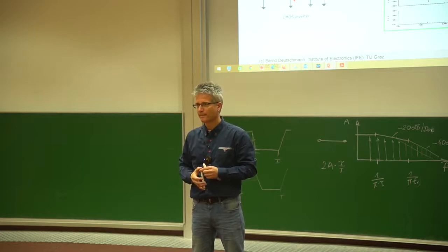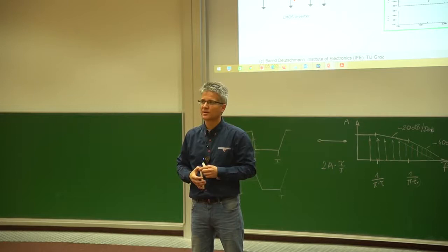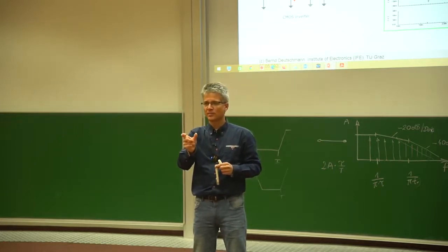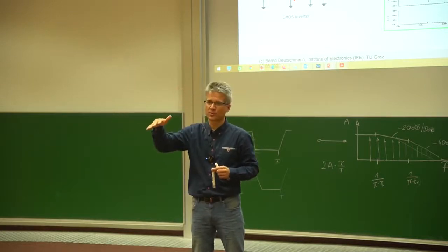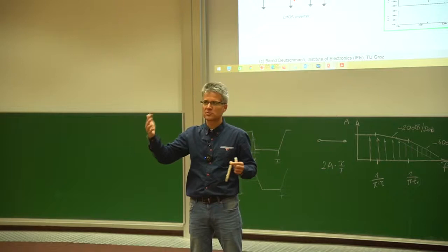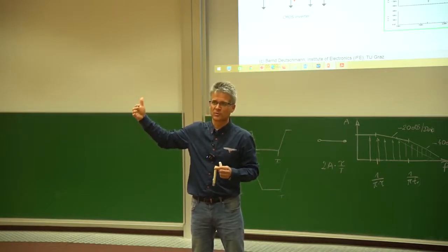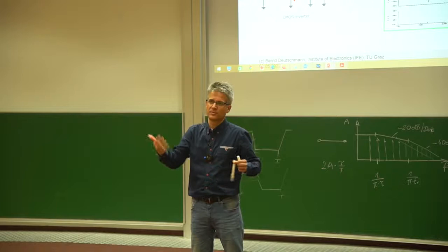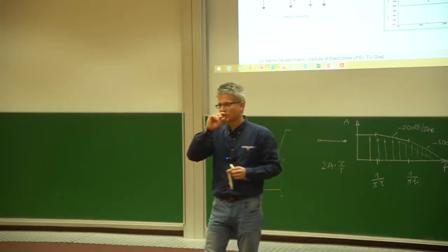Small resistance. Okay. But if the resistor is then there permanently, and we are driving, for example, a high signal at the output, we always have a voltage drop across the resistor, which can be a drawback because the output signal is then not 3.3 volt or 5 volt or whatever anymore. And also the heat dissipation, so the IC will definitely heat up a bit more. But resistor is the right direction.